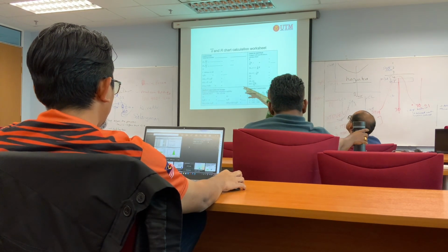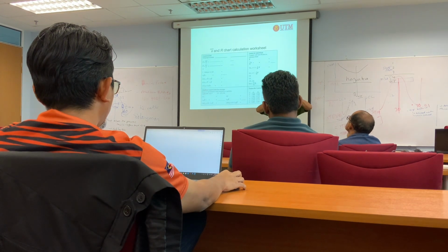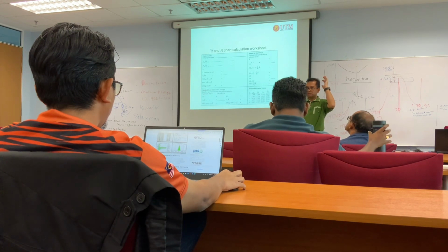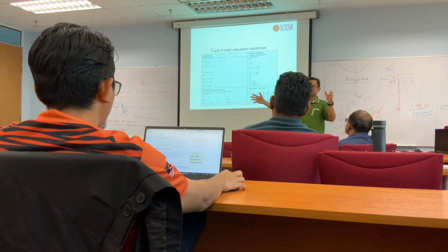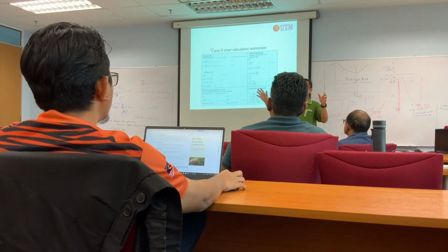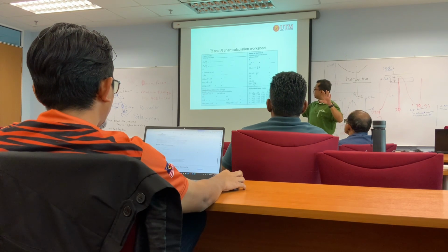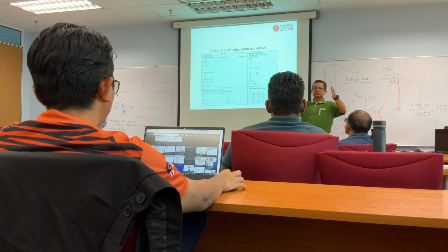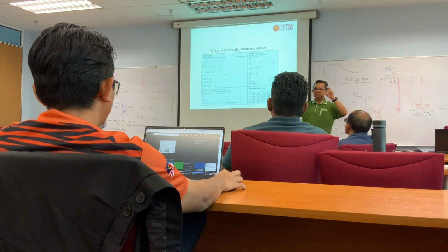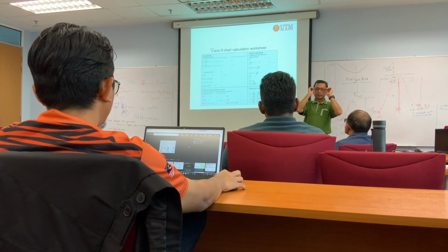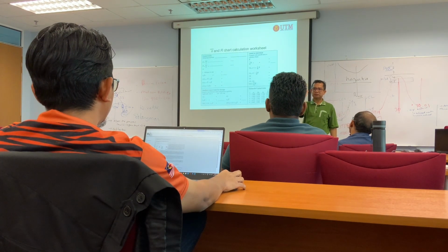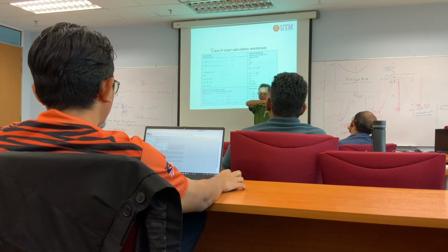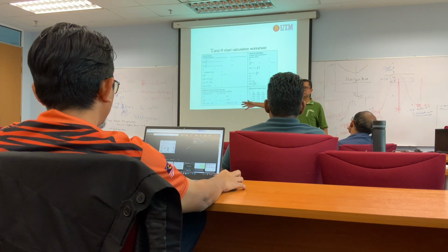But pertaining to the R bar, it still depends on your data. It's really unfair if you take the R bar for that particular week or particular month. So I am advising you, if you want to compare, of course from this plot your R bar should be that particular month's R bar. But if you want to check whether you maintain the level in terms of your 3 sigma, you have to compare this R bar with the entire year, the whole year.